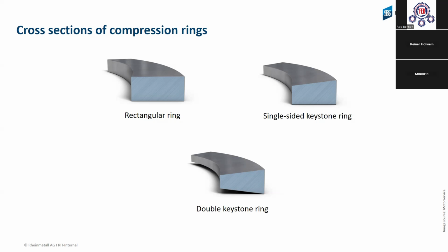In this situation, the carbon will not only be on the piston crown, it will also build up in the first ring groove of the first piston ring. And when there is carbon inside, the piston ring cannot move. This is also very important. Each piston ring must move in the ring groove of the piston. Or when they stop moving, then we have a problem.